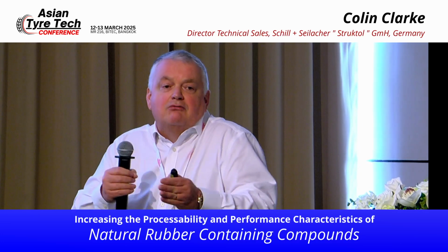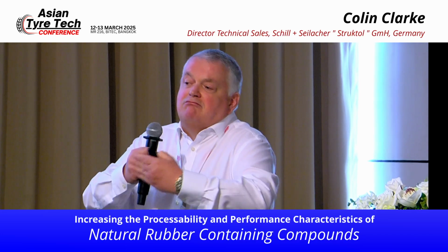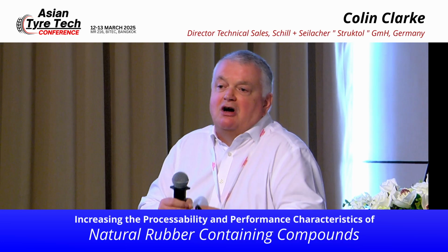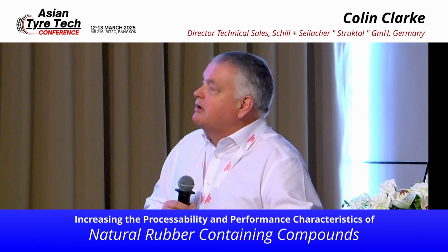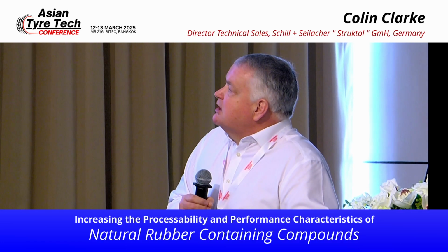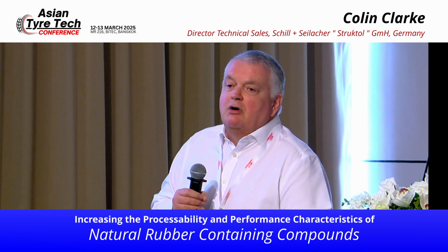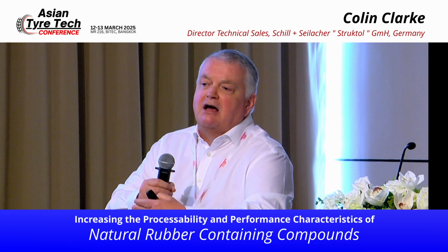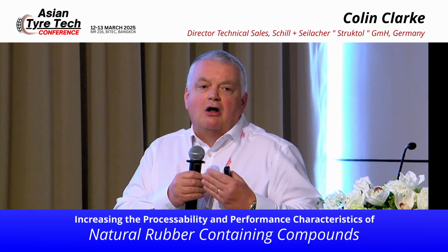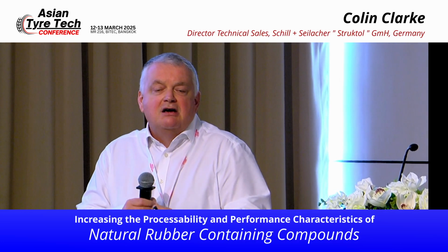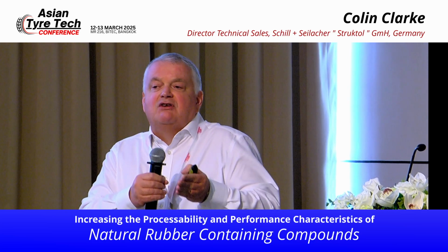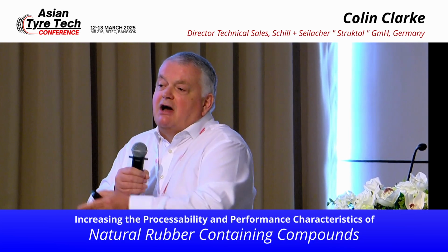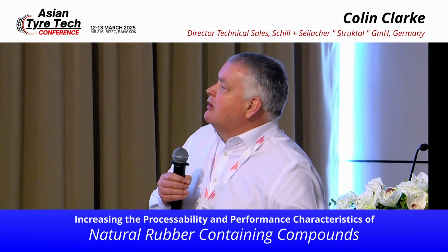So actually, can we really maximize the behavior, if you like, the way of working of the peptizer by changing the technology a little bit? So actually, new technology, we call the product HT105. It's a series of new generation peptizer, natural rubber breakdown chemicals that is much more tolerant of the presence of carbon black, and in a way will much more selectively target natural rubber and will not cause any adverse breakdown towards the synthetic rubber components that you have.